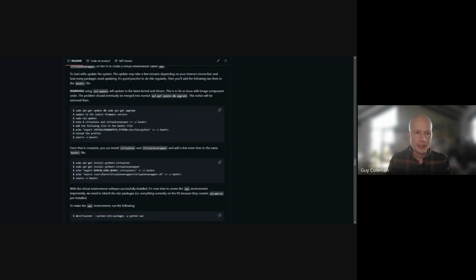And then the most important part is where you start installing and setting up the virtual environments. Also, probably the most important part at the moment is this line here, called sudo rpi-update, because unfortunately they made a bug, which I was talking about previously, with RGB cameras. In the libcamera library, getting to the very technical stuff, they use a format called RGB888, an 8-bit RGB format, which is what the Raspberry Pi software uses to make sure it's in the right format for OpenCV, which is in a BGR format.